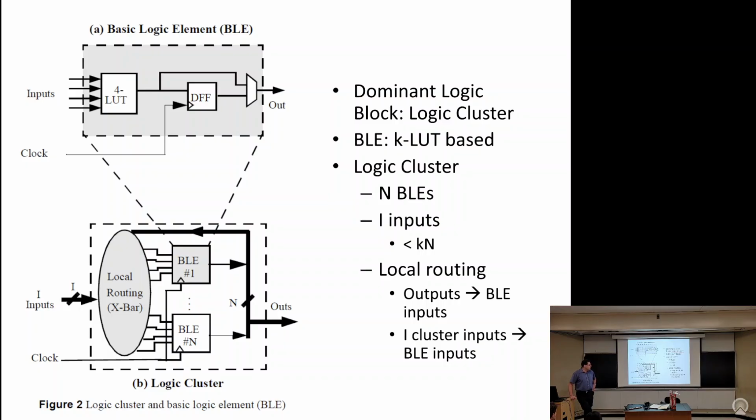So the only FPGAs I know that go hierarchical through the whole array nowadays are basically embedded FPGAs. There are a couple of companies that make embedded FPGAs where they're not intended to be too big. They're like a few thousand lookup tables, and they can actually make that completely hierarchical. So basically like what we showed on the whiteboard. If you go much bigger than that, all the problems that we talked about of some really long wires and stuff come to play.